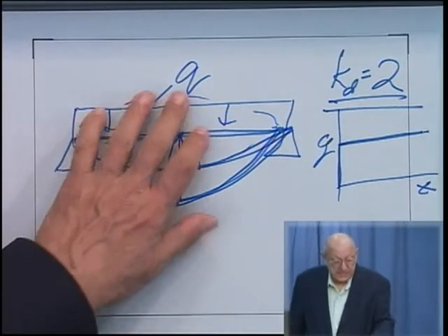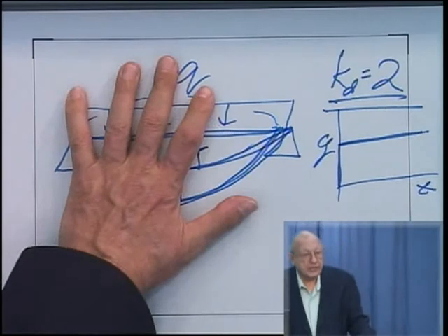But in this case, and this is a typical, well-known case, when the same load is applied dynamically, it is worse and results in higher stresses than a static load. But there are also cases when it's just the other way around, when dynamic loading is less dangerous, less detrimental than static loading, because the system simply doesn't have time to react.